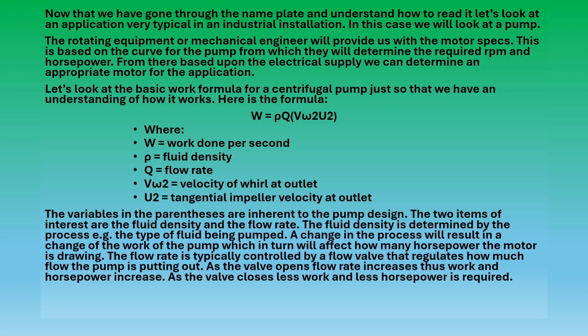In the instances, as previously mentioned, where I've seen us go to 140% for the motor overload on a temporary basis, it was because of one of these two factors. And again, we did that temporarily until we could get a new motor spec'd out, designed, bought and installed to handle that change.